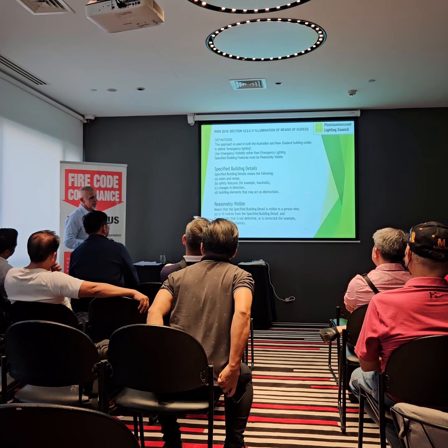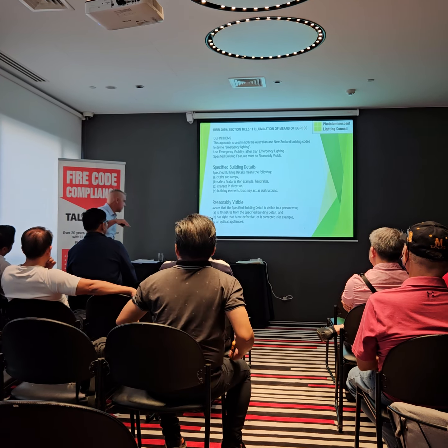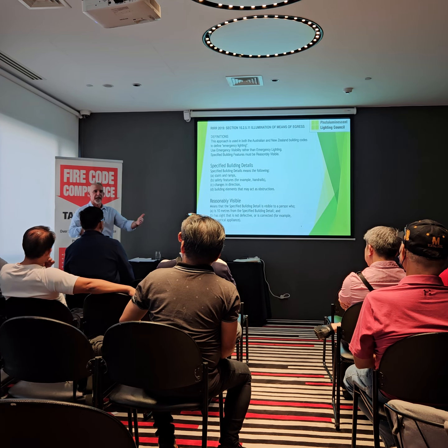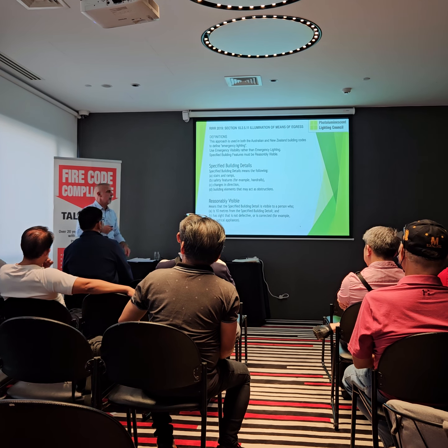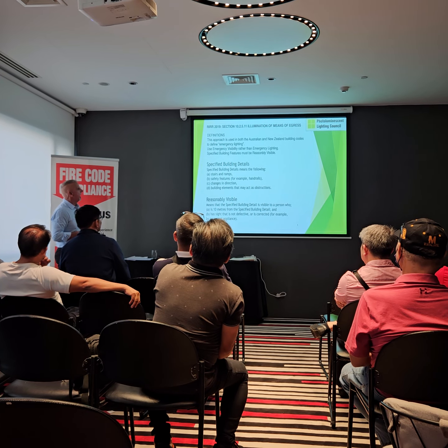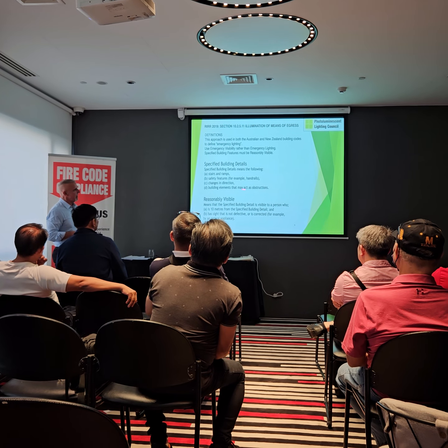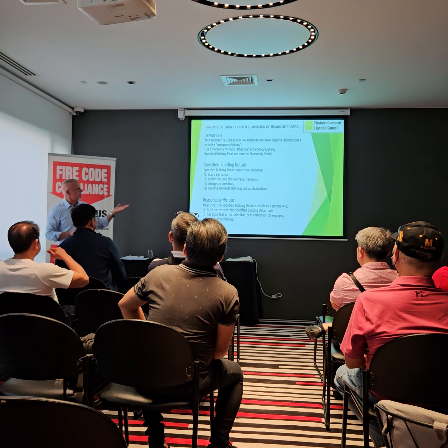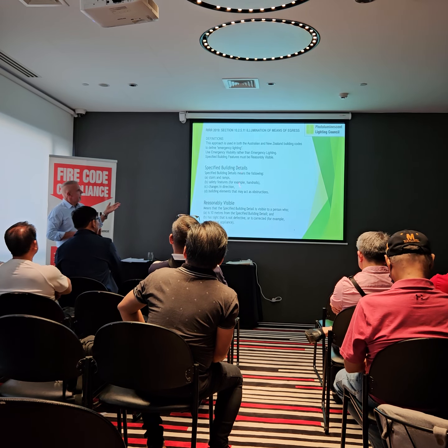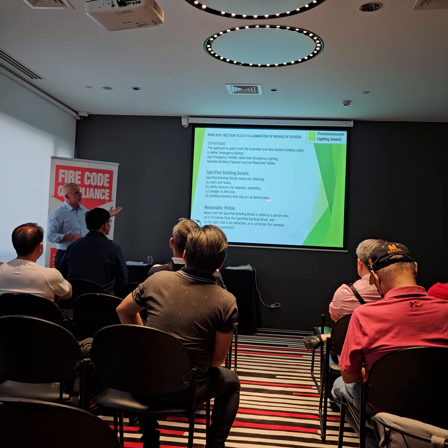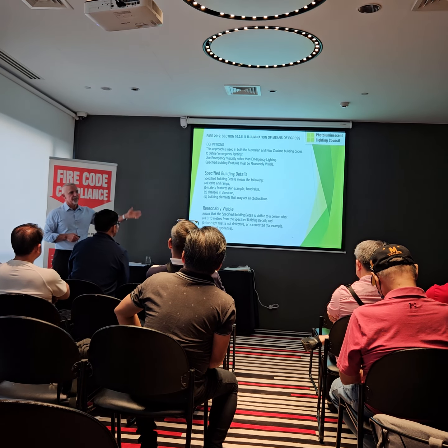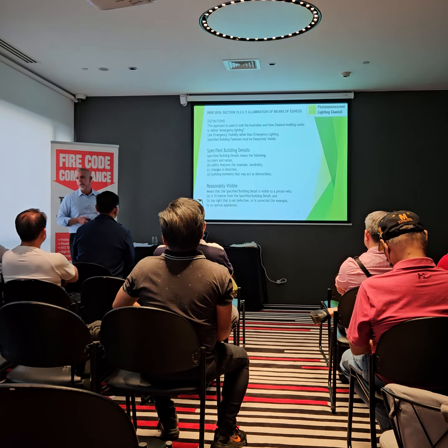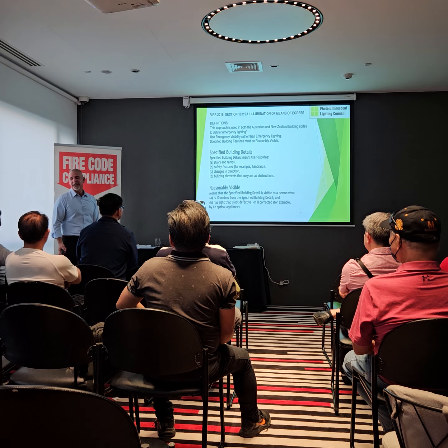Changes in direction, if you remember, when we were coming down through the stairway, at the switchback on the stairs, you have the landing perimeter marked, and any obstructions you need to mark with a piece of photoluminescent material. Most common in emergency stairways might be standpipes for the firefighting water. Yeah, yes, so yeah.